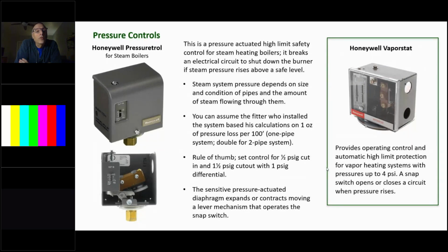And with those types of systems, they were designed to operate on ounces of steam. They usually had larger pipes, and at night the owner would bank the coals in the boiler and allow them to operate on very low pressure throughout the night and keep heat going in the system.